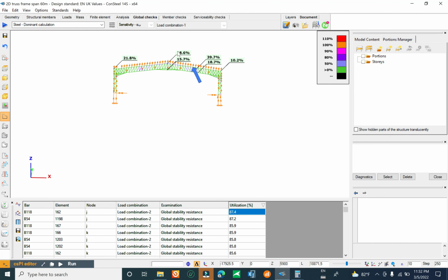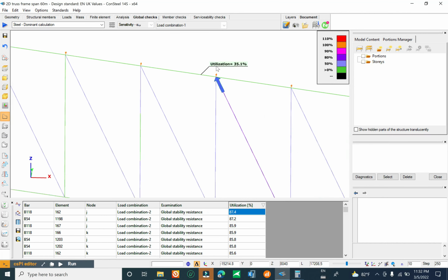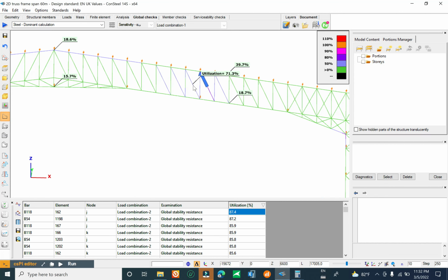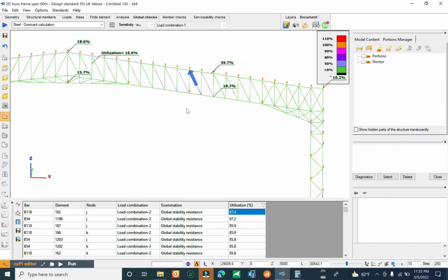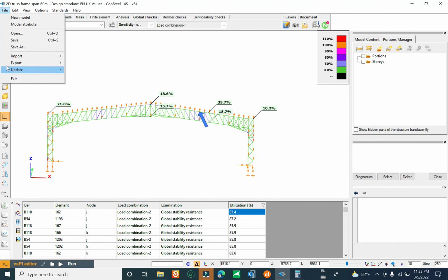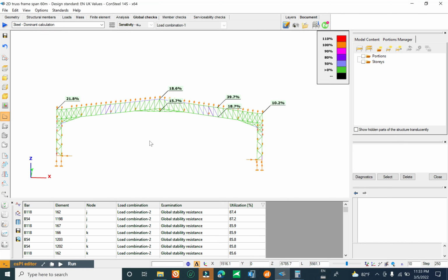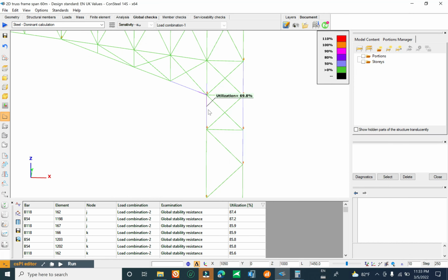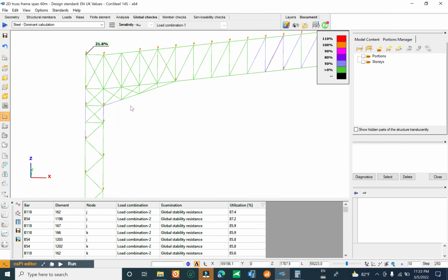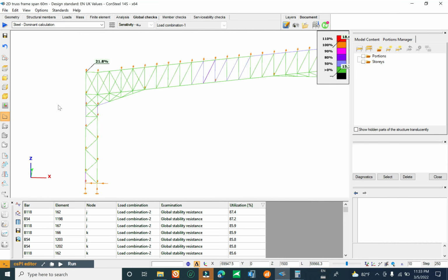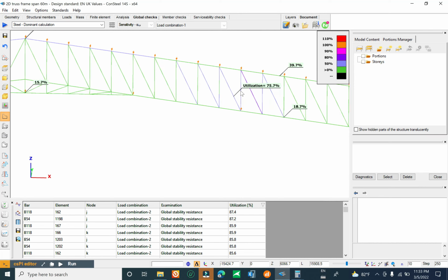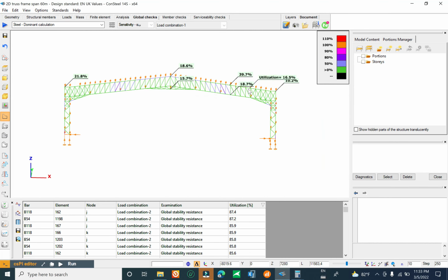Okay, you see here in the joint, on the node C or element 132, this element is 132, and the joint is the location for the maximum design ratio. And you can check everything on your model. Okay, let's see the steel design calculation and general elastic for the elastic design.